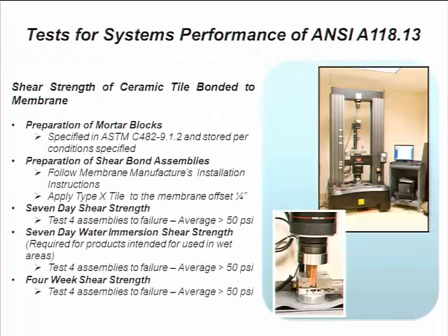And one thing I would point to in this industry: be sure that you look at how the manufacturer reports the specification, because in some cases they may say it meets X property of the specification, but you really want to meet the entire spec or it is not applicable. The product needs to meet every category of the specification. As we talked about, it's a minimum spec at best. So if they're only reporting one element of meeting the test, it should be a clue to you that you need to check further and contact the manufacturer to ascertain that it meets all criteria within the specification.